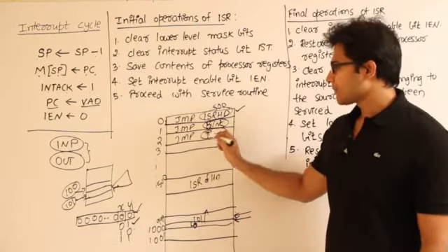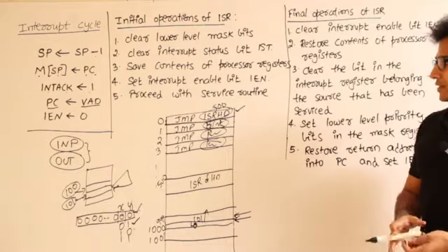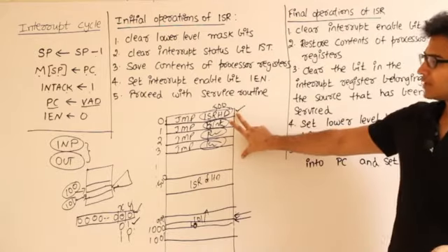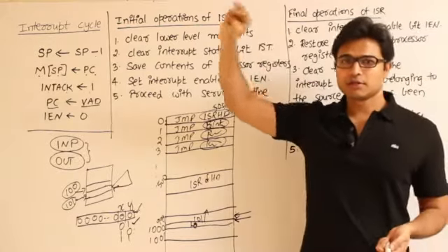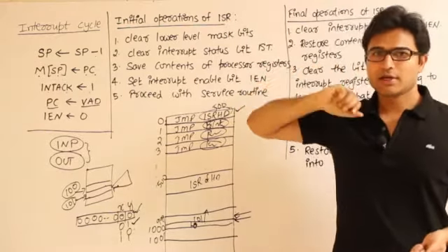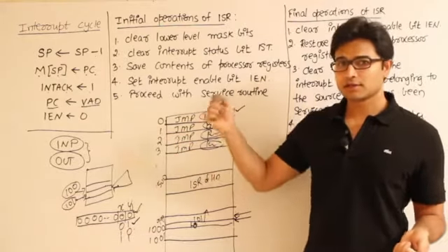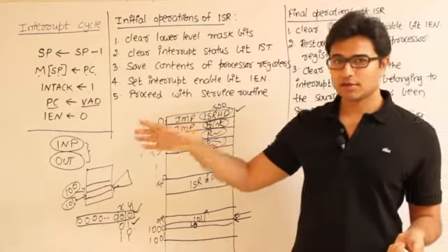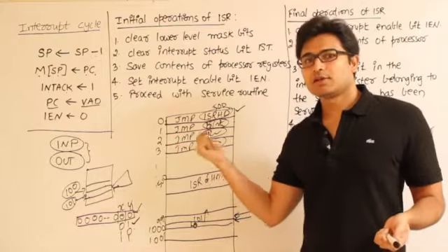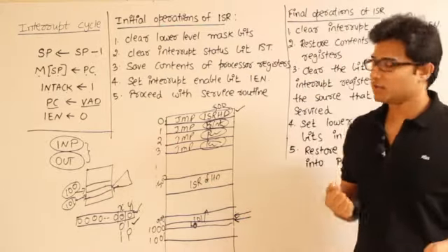So like that, if you have, let's say, 8 devices, then the first 8 locations will be filled with that. Then the encoder is supposed to give you 3 bits. Got it? In the example we had discussed with 4 devices, that is why we have an encoder with 4 inputs and 2 outputs. If you had 8 devices, then your encoder will have 8 inputs and 3 outputs. Got it? That priority encoder.